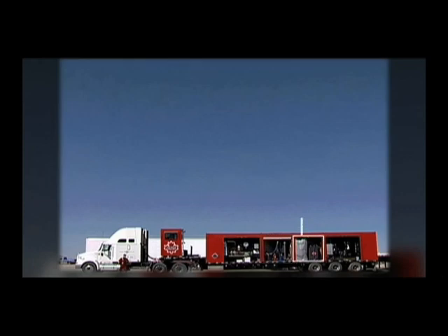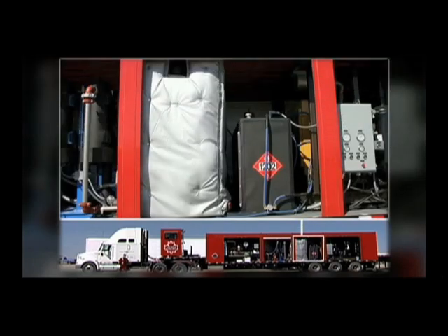The purified air then proceeds to the air separation membranes, which allow oxygen, water vapor, and carbon dioxide to permeate the walls of the hollow fibers, leaving a high-pressure concentrate of nitrogen. The nitrogen is collected in a manifold and directed through the back pressure control valve. A product valve vents the flow of nitrogen until purity reaches the minimum requirement.